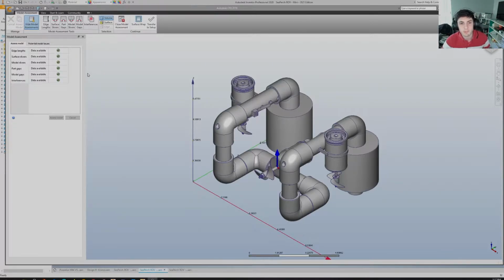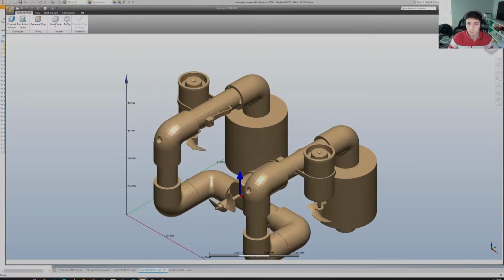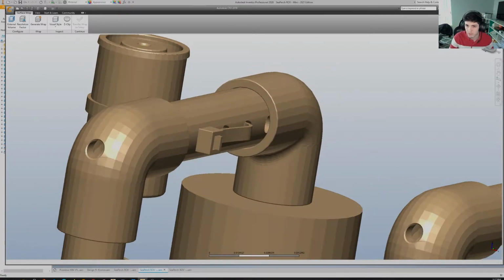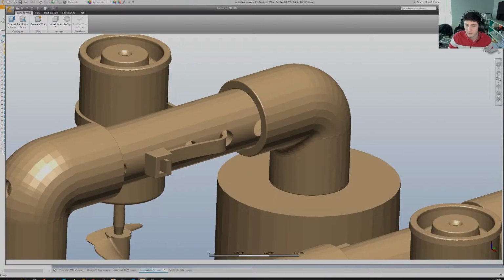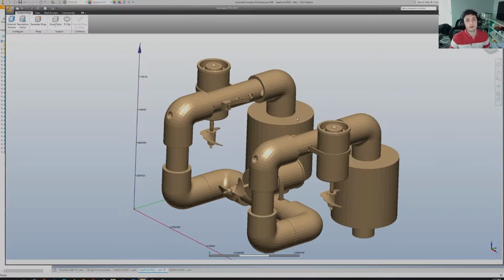Alright, so the model assessment has completed, all green checks like you'd want to see. So we're going to click surface wrap. Surface wrapping is useful. It has a higher chance of working than traditional meshing because it eliminates a bunch of small details that would normally not be friendly for simulations, like very small gaps between, let's see, this pipe and this L joint, and other small details that won't affect the overall results but will help reduce the computational time of the simulations.